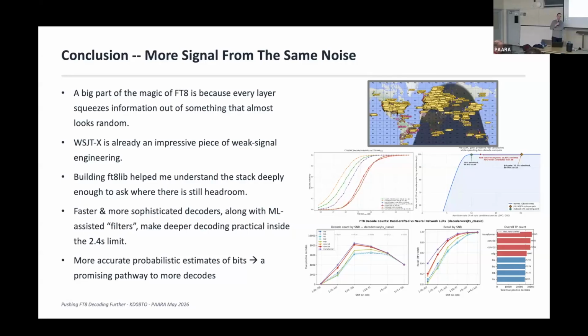Oh, I mean, all right. So this is getting into some inside baseball. There are papers which I've read, and I even corresponded with one of the authors. With a neural network, you can put in somewhat arbitrary computation, and you could even take the LDPC code, which is essentially defining a relationship between the payload bits and the parity bits, and try to use the LDPC code in the demodulation step itself. Yeah. And so we're called code aware.